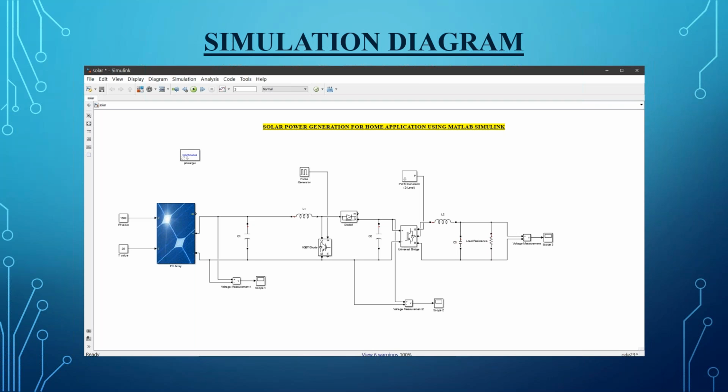I explained the working principle of IGBT before. There are 4 IGBTs connected in this bridge. We are giving the pulse to 2 IGBTs at a time. So first, when we give the first pulse, it will create positive AC voltage, and then when we give the second pulse to the bridge, it will provide negative AC voltage. In this way, it will generate a proper AC voltage. This is the simplest explanation of this universal bridge. I can explain the full working principle of this bridge by drawing it, but I have limited time, so I am not able to do it.